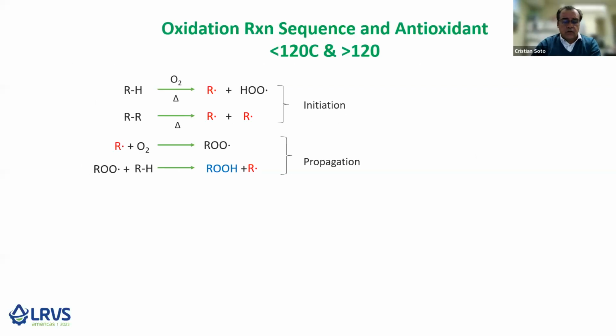So let's talk a little bit about some aspects of oxidation which will be relevant later in our presentation. There are many different ways of looking at oxidation. I like looking at it in the manner I'm presenting. In essence, the RH in this set of equations represents the lubricant, which upon heat and the presence of oxygen and/or water will form free radicals of the hydrocarbon and also peroxy radicals.